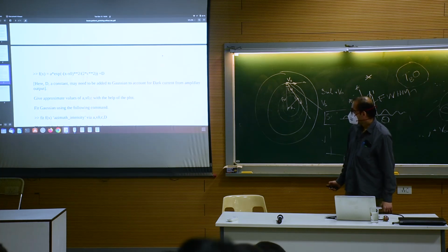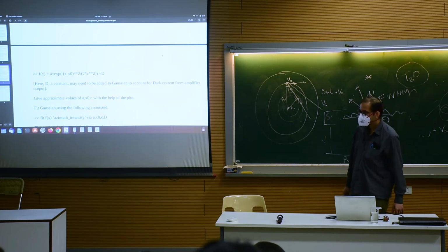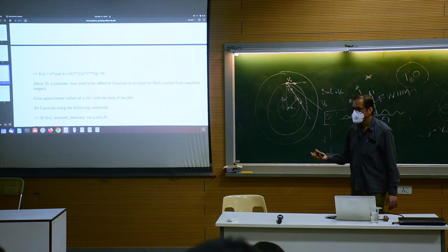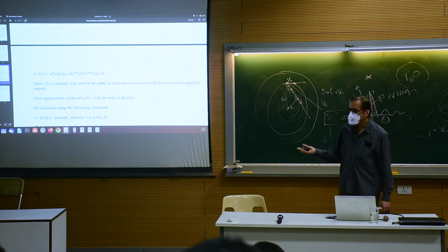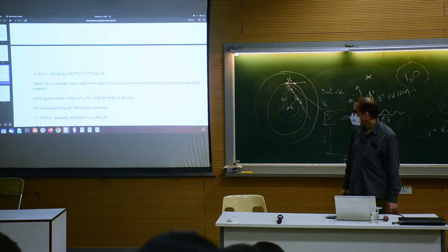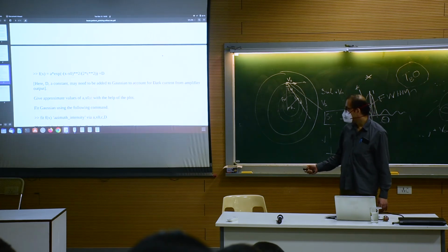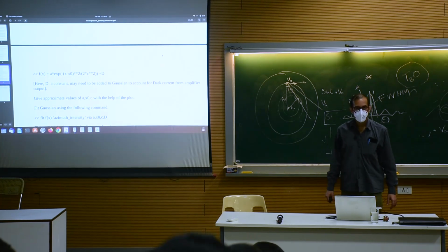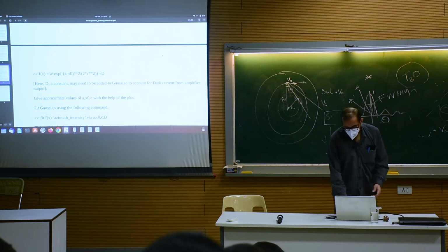So you are fitting that f(x), whatever you have decided, to the azimuth intensity data, which has 2 columns. One is in degrees, and the other is the intensity converted from dB to linear scale: 10 to the power 0.1 times the gain in dB, that formula I showed. Via these you fit the unknown parameters. So that's all, that is what you will be doing.